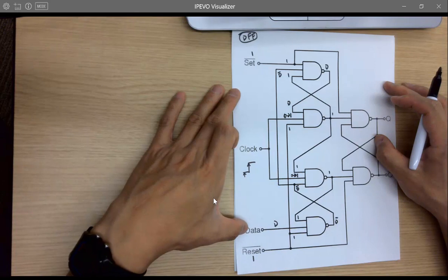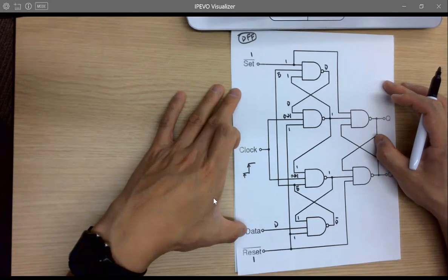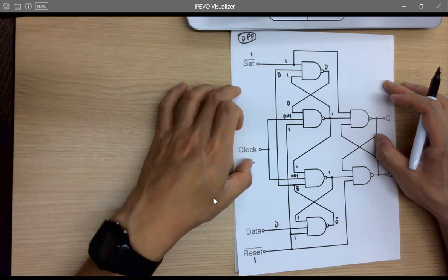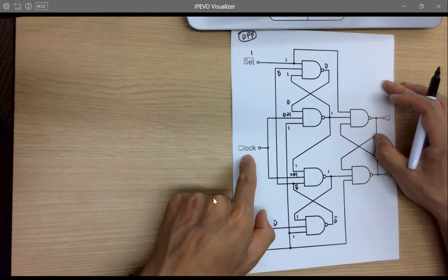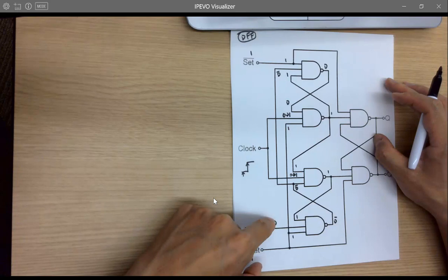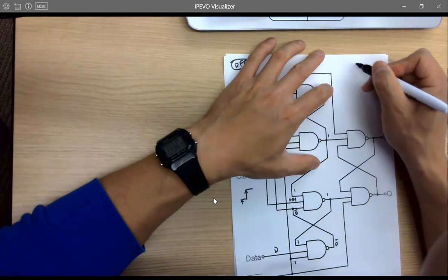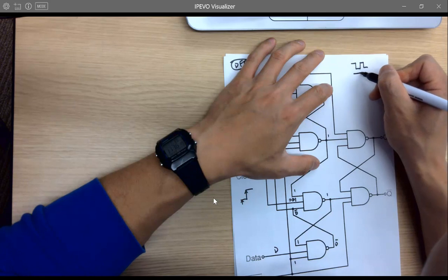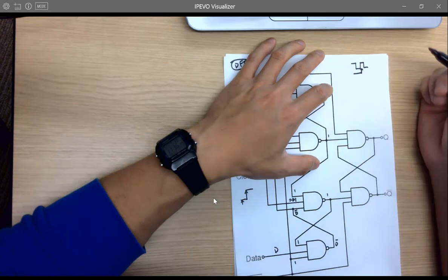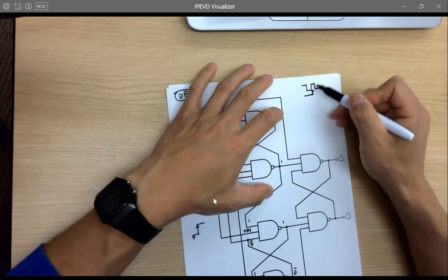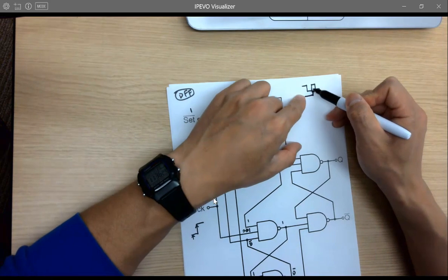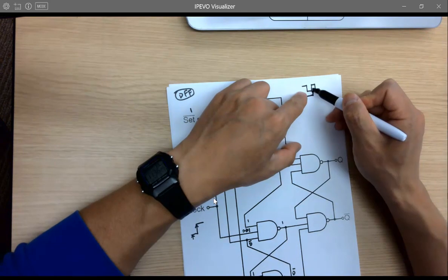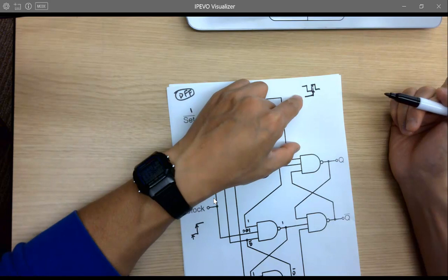No, we are not. It's going to be too many variables, right? Because the reason we are looking at the rising edge is because we are assuming the rising edge is really fast. So D must be stable, even though sometimes, for example, D is changing like this, and you are sampling, so the rising edge is over here, right? It's still not at the edge of the D, so D is not changing. You are still sampling the DC voltage. You know what I mean?